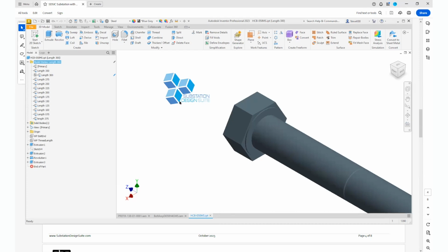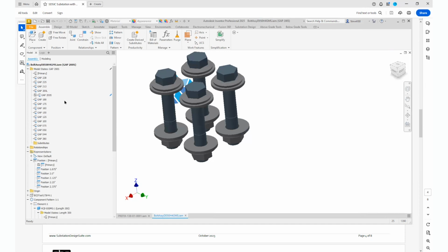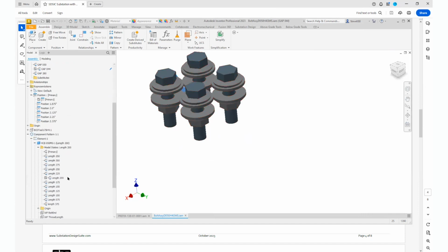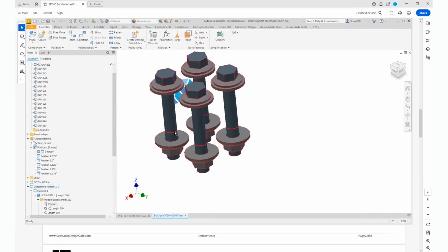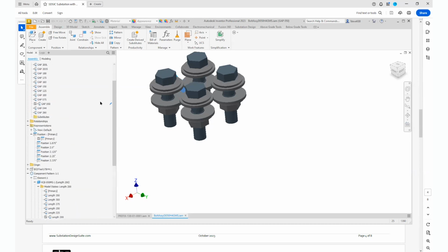As it goes into the parts list, the parts list is going to update to show the correct part number, description, and everything we need for it. So if I change this to, let's say, a small one, that bolt length has changed now. That bolt length is now, I don't know, it's not 2 inches. I don't know if it updates for us down there or not. Let's go up to the long one. You can see how that bolt length is changing. So here it's 350, so that's 3.5 inches long. And if I come down to a small gap, I have it set to only 2 inches long. And you can change that. You can set it up whatever way you want. You can use grip instead of gap, but you can see what I'm changing in here.